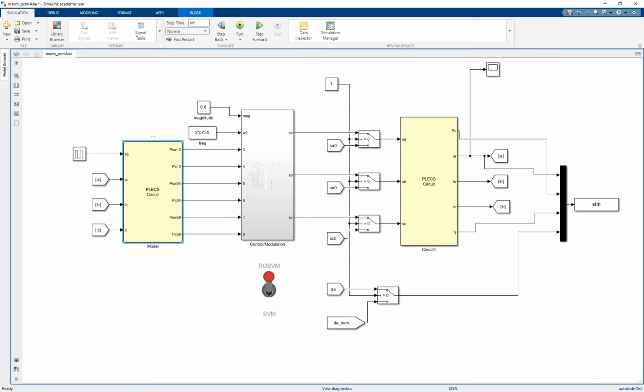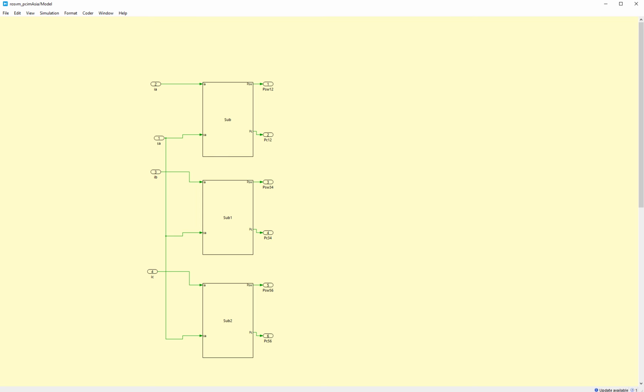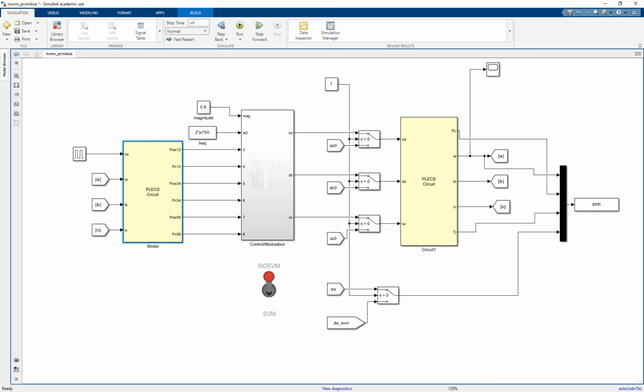And through this simulation, I can actually calculate the power losses. But these are the power losses for 50% duty cycle. So I have to work out and simply divide it by 50% to get the instantaneous power losses. Because this modulation or control only needs to know the magnitude of the power losses, or instantaneous values of the power losses, and redesign the duty cycles accordingly.